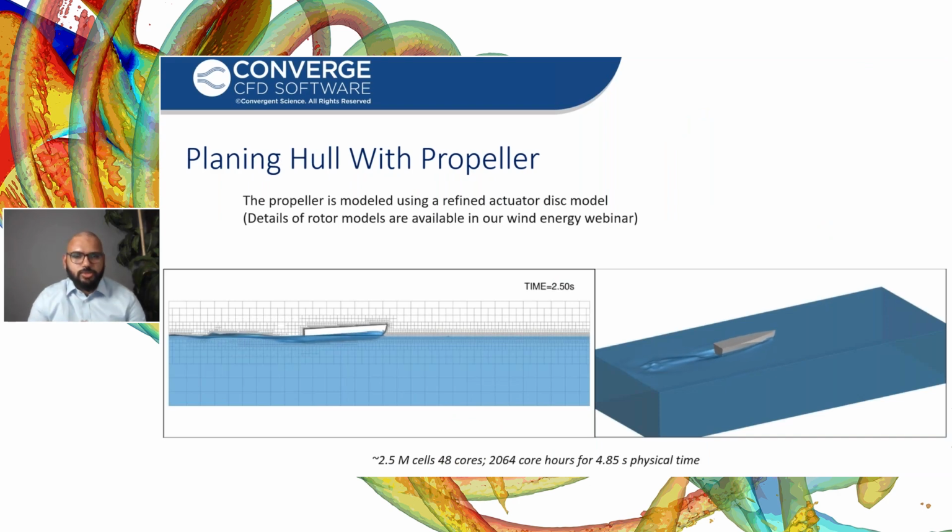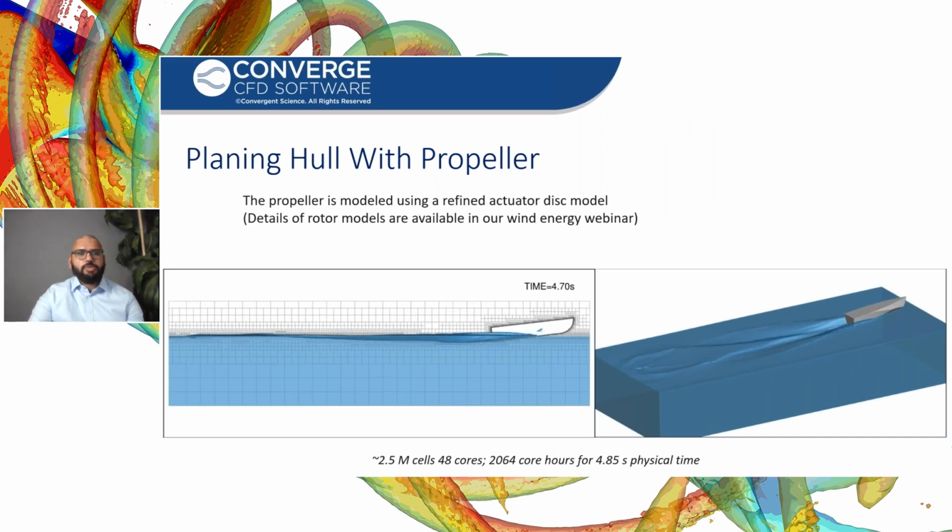We can also do planing hull simulations with the propeller. We have different models for modeling the propeller. In the last slide, we saw how we can explicitly resolve the geometry and calculate the forces acting on the propeller.